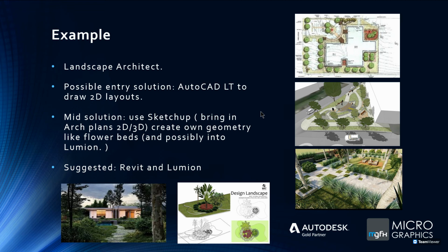So it's a very entry level solution. Yes, you can add colors with the hatch and that sort of thing, so it looks good, and that is a possible solution. Now, if you want something in 3D, you'll have to look at something else, maybe SketchUp or Revit. You can get away with 3D in AutoCAD, but the drawing side is a little bit chunky and slow. So I'd rather suggest, if you're looking at 3D, either SketchUp or Revit.